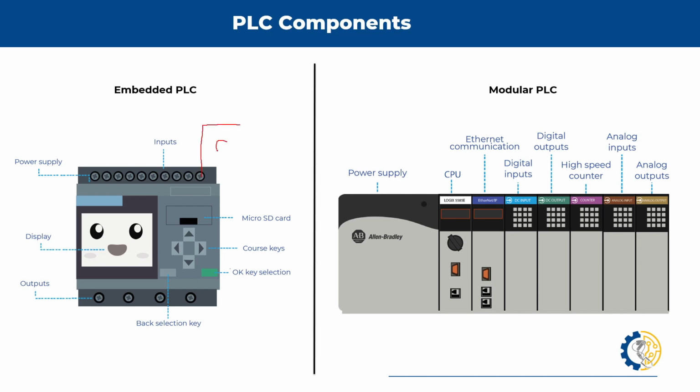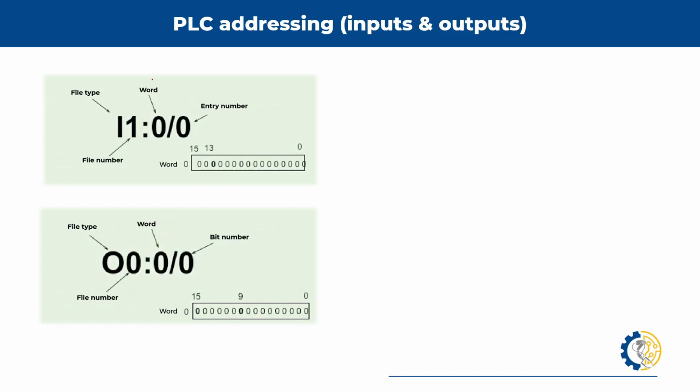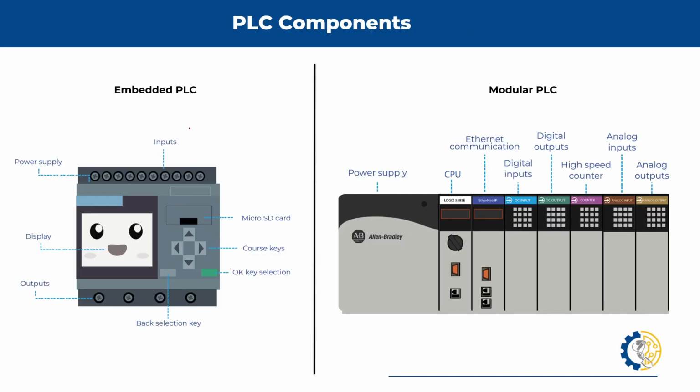Let's suppose that this is our point, and I'm going to connect here a contact, okay? If we energize our contact, I'm going to assign here a PLC voltage. If the PLC detects that voltage, I'm going to run whatever action or activity. So then, our last digit is going to help us identify our point number, which in this case, with our modular PLC, if I connect something to my point 0 or my 0 point,